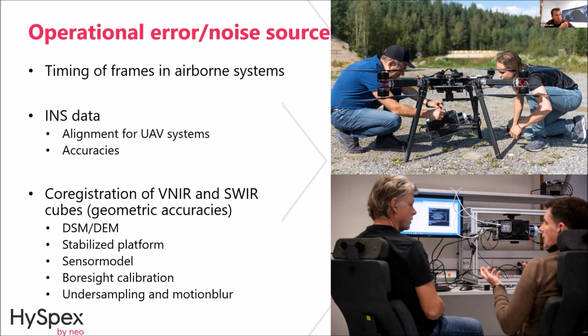For a drone system, for example, if you're flying for 30 minutes, you don't want to spend a lot of time on that, so you have a different procedure. You fly up, you fly straight very fast for 20 seconds, you stop and you come back, and then you're aligned. So you use 40 seconds to align it. You do your campaign, you do another alignment before you land, and then you're done. To fast get the INS system to a very good state.